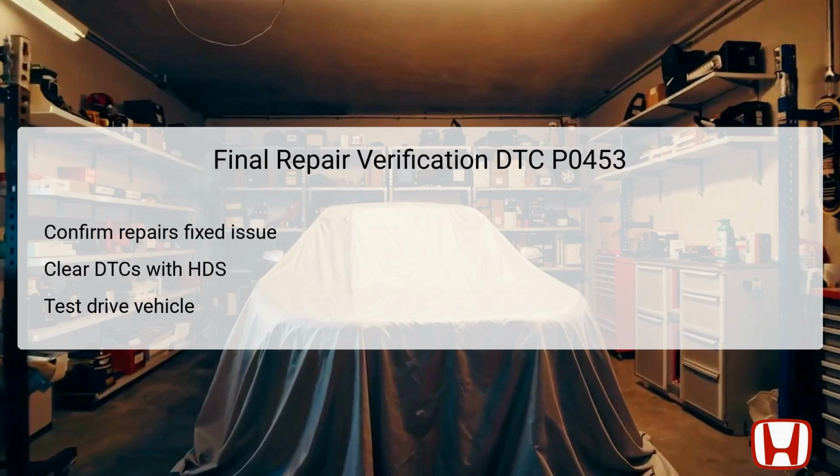To finalize the repair process for DTC P0453, you need to conduct a thorough verification. First, ensure that any repairs made have indeed resolved the issues by rechecking FTP sensor functionality and the entire circuit associated with it. After confirming successful repairs, proceed to clear all diagnostic trouble codes, DTCs, using the Honda Diagnostic System, HDS. This action resets the fault memory and allows the system to enter a new learning cycle.